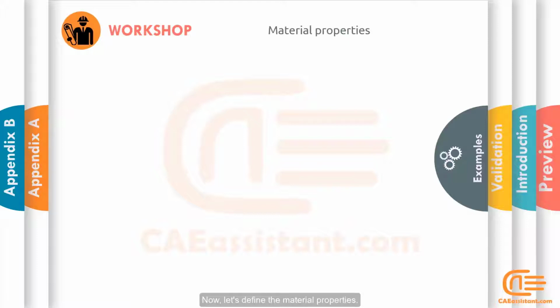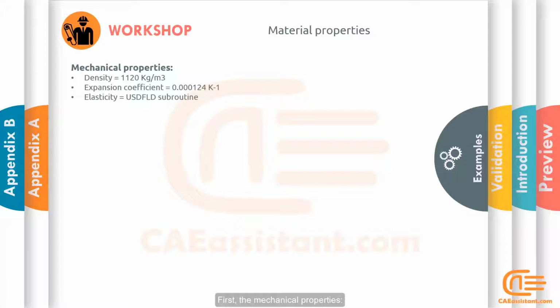Now let's define the material properties. First, the mechanical properties. Density equals 1120 kilograms per cubic meter. The expansion coefficient equals 0.000124 per Kelvin. And the elasticity will be calculated by the USDFLD subroutine, because in the 3D printing with the stereolithography method, the elasticity is not constant and will change during the process.